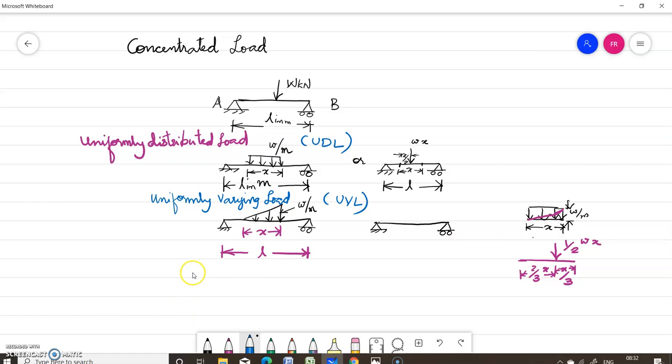Okay. So what is indirect loading? It is possible that a force response as well as a displacement response may be induced in a structure without being caused by externally applied direct loads. We may use the term indirect loading to refer to the cause of such load effects. Usually this type of loading occurs in addition to direct actions. And if this is not anticipated in the design, it may result in serious consequences. So a structural engineer should be able to analyze the response caused by such indirect loading.